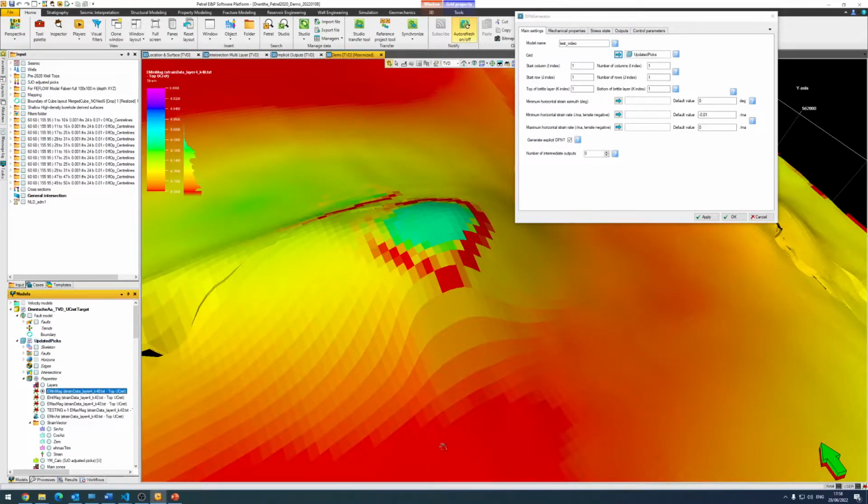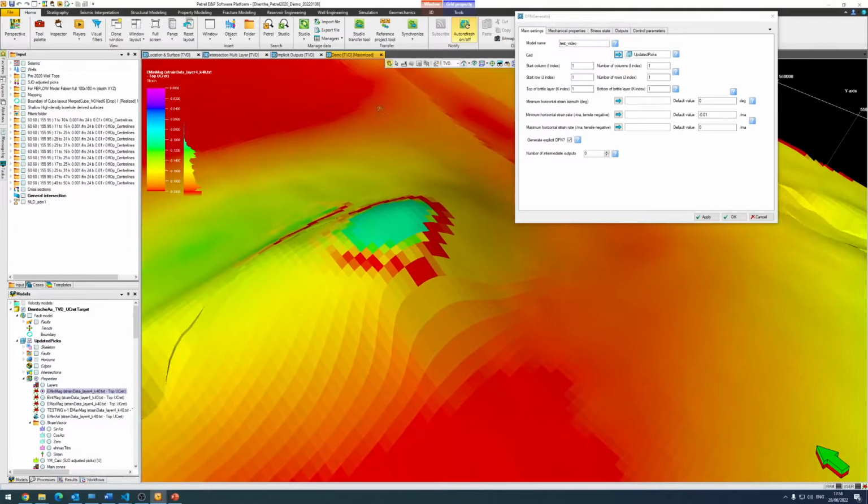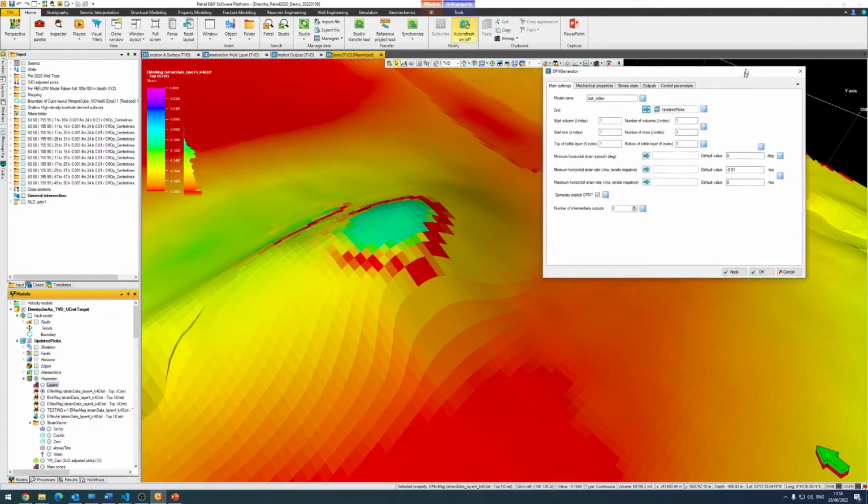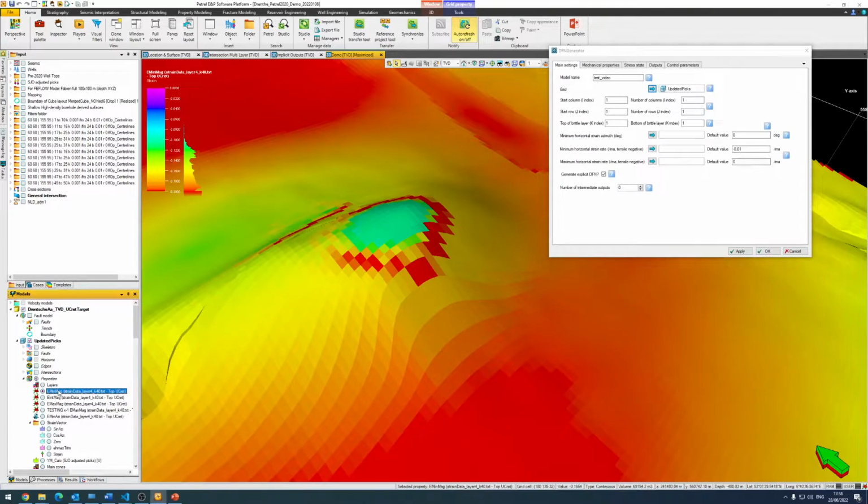So to do that, I'm just going to pick another view here, and if we use the select tool, click on a cell while we have a grid active, then down on the bottom right here we can see that there's a grid cell parameter, and that's giving us the coordinates in I and j of the cell that I've just clicked on there.